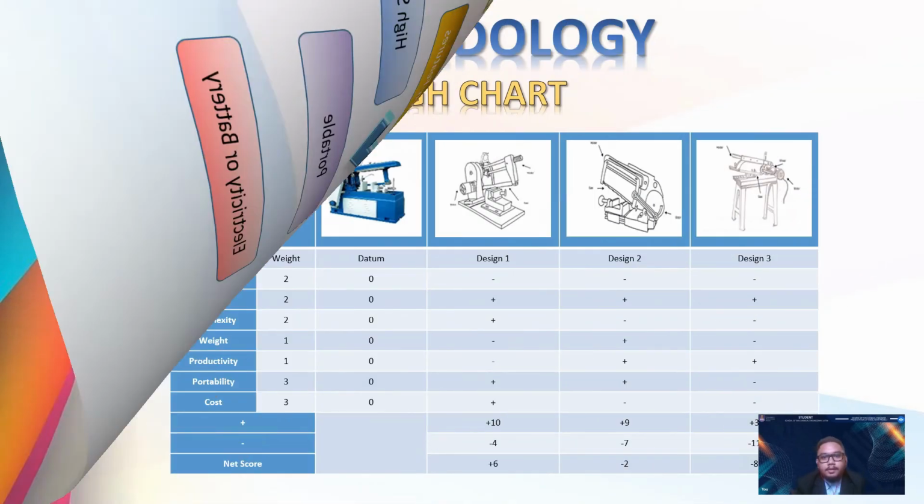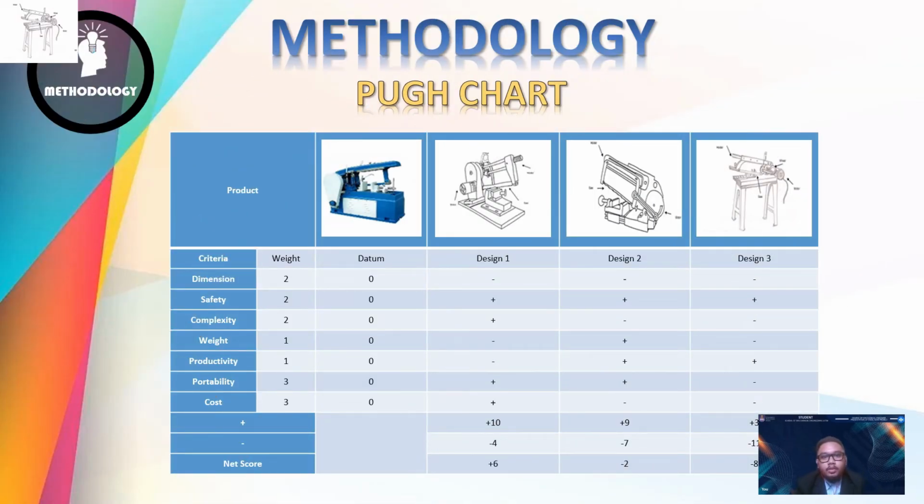After we have the conceptual designs and evaluation, we can go through to the process of the proof chart. Early in the design process, a proof chart is a simple design tool for comparing the design concepts to your design objectives. Each criterion, like in the left column, is given a weighting based on its importance. In this section, every criterion has been given a value: the important criteria are valued as 3, and the less important will be weighted as 1.